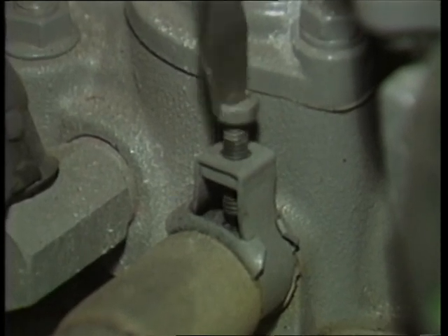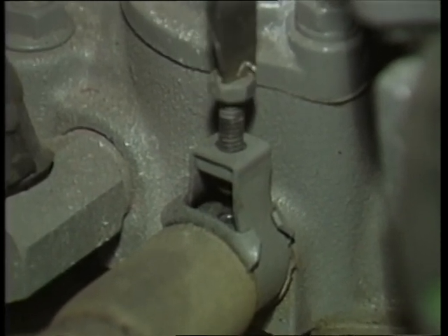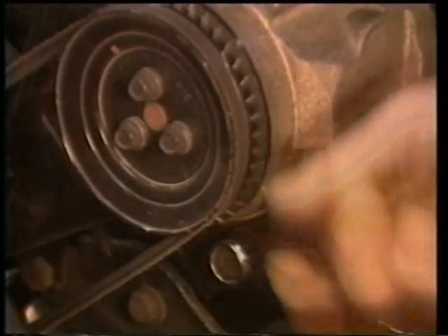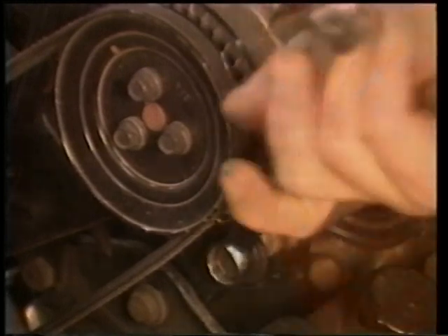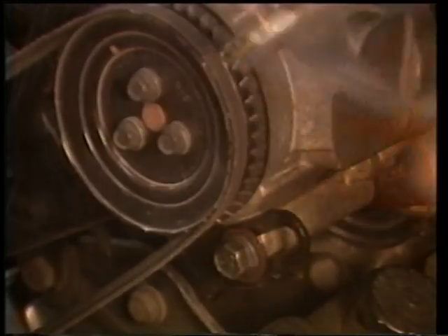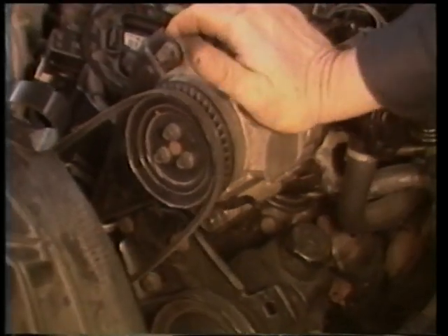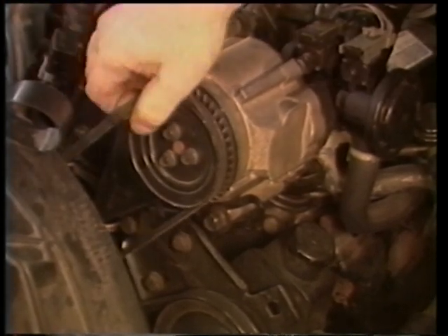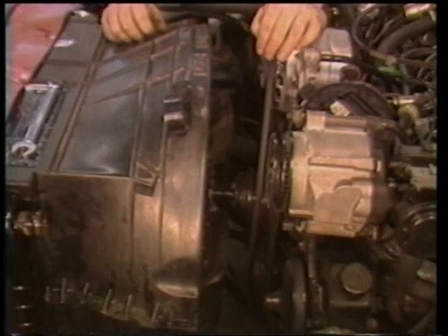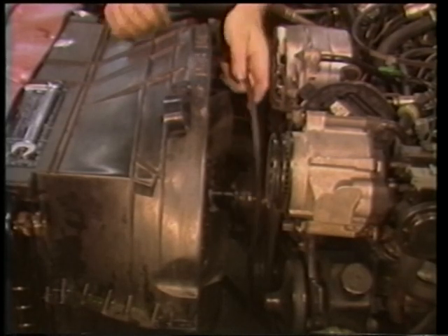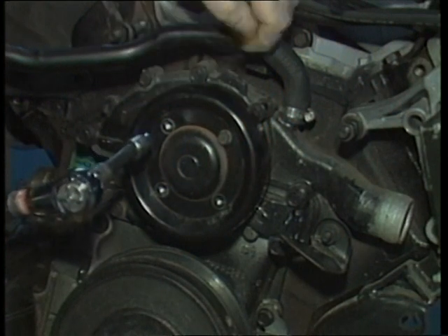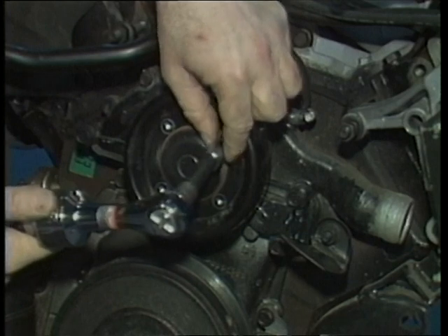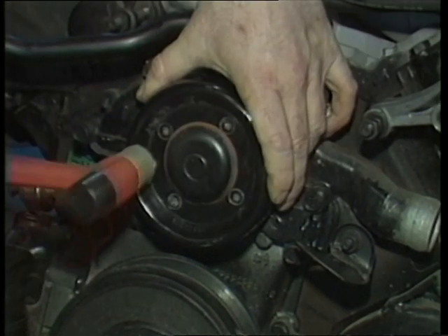To replace a water pump, remove any hoses going to the pump, like this bypass hose. Remove any fan belts that go to the water pump or that block access to the pump bolts. Depending upon the design and location of the water pump, you will have to remove various parts in front of or bolted to the pump housing. Refer to a service manual if needed. If available, always use an air ratchet when working on a water pump. It will fit down into the tight quarters next to the pump.